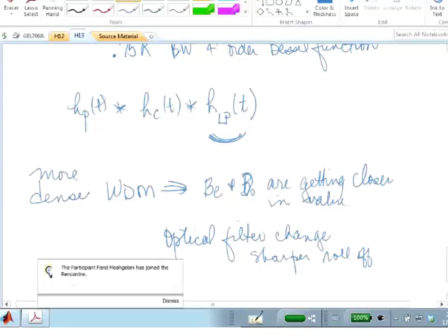It just depends. But the problem in optics is that the speeds are so high that running an adaptive filter is prohibitively expensive. Maybe with coherent detection systems this is less the case, and maybe we'll see this more, but there are already fixed effects that would have to be treated in DSP, and now getting time-varying ones would also be difficult. So maybe it's a compromise between what's actually going on in the system. Like I said, it depends which channel you're talking about, and what you're willing to pay for in terms of processing.